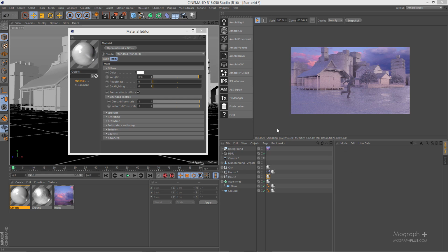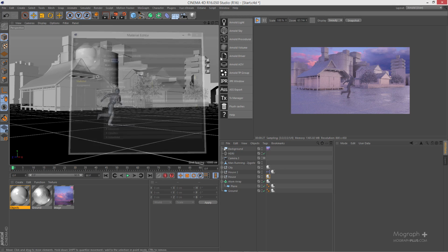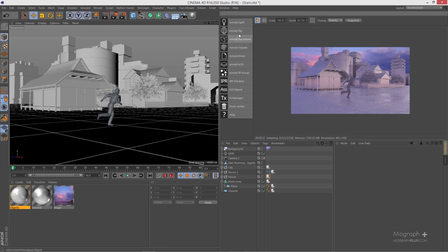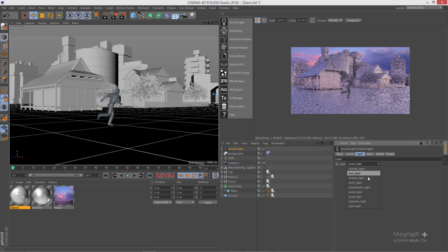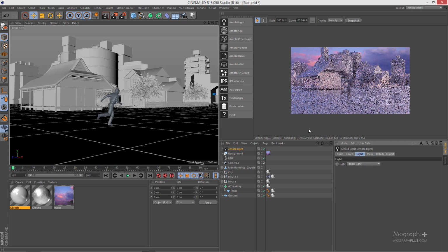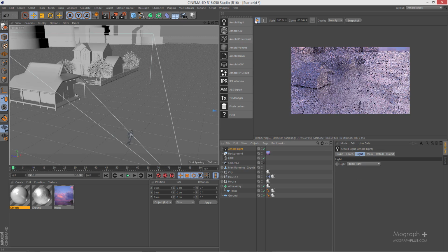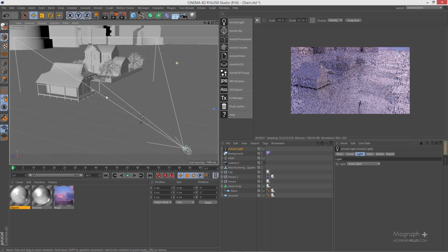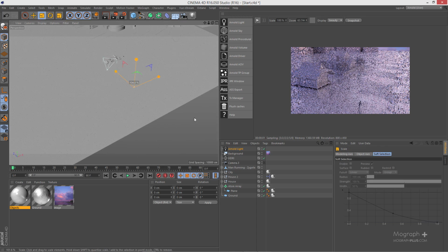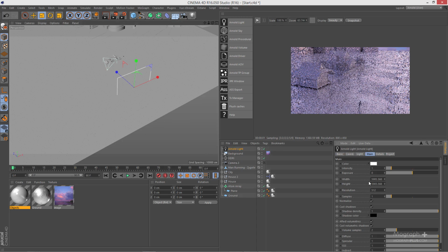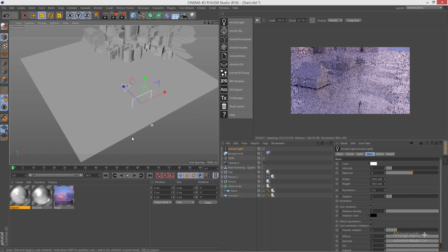The next thing is actually I want to add some volumetric effects, and in order to do that, let me first create an Arnold light, which is going to be an area light, and let me get out of the camera here and also stop my IPR. Okay, let's just get out of here. I'm going to increase the size of my light quite significantly. If I select the light and go to the main, you can see the width and the height of this light.